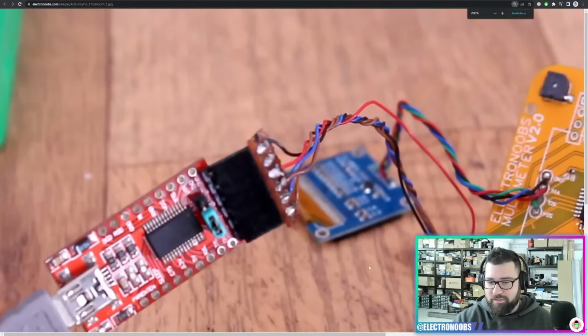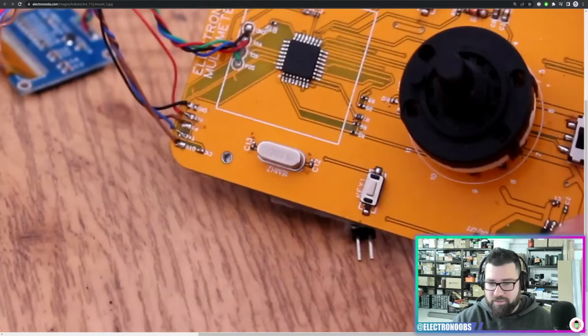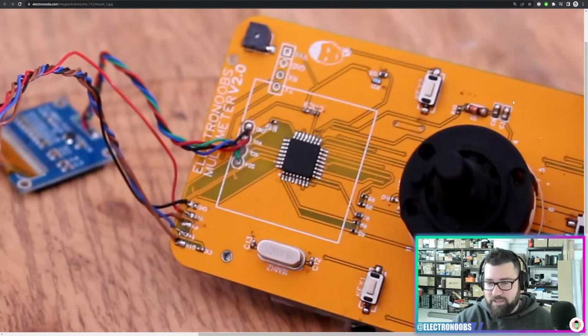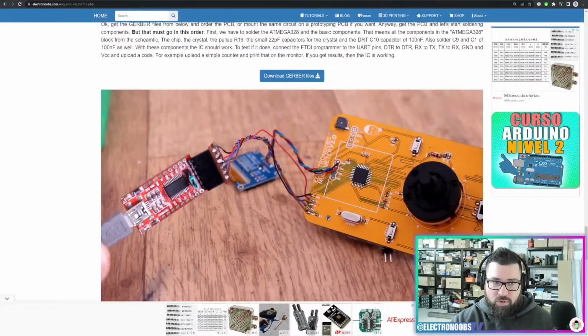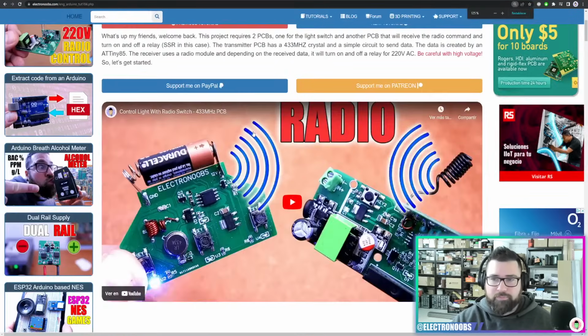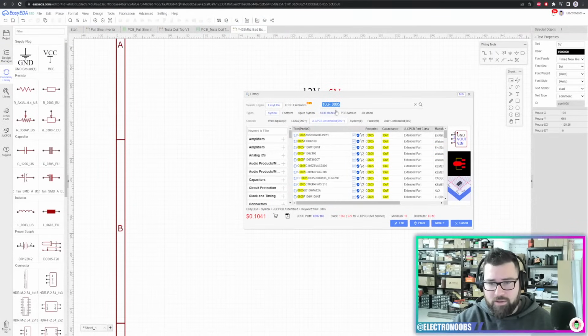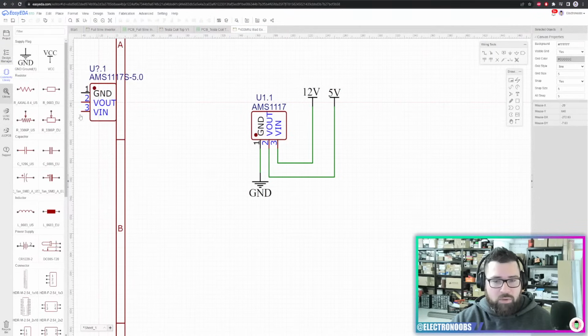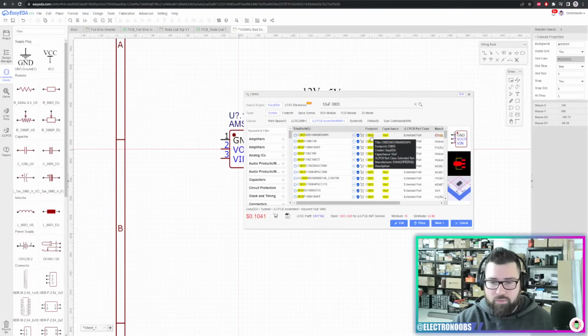Open this in a new tab and just zoom. So this is a 0603 and this is a 0402. Look how small this is. It could be very difficult to solder using your soldering iron. So that's why usually I don't use 0402. I just go with 0805 for the 10 microfarad, and if it's something smaller, I will go with 0603.